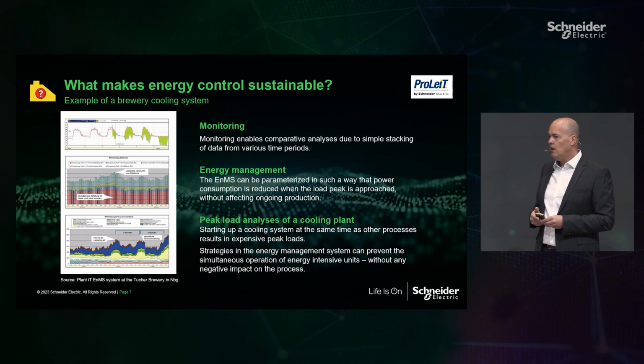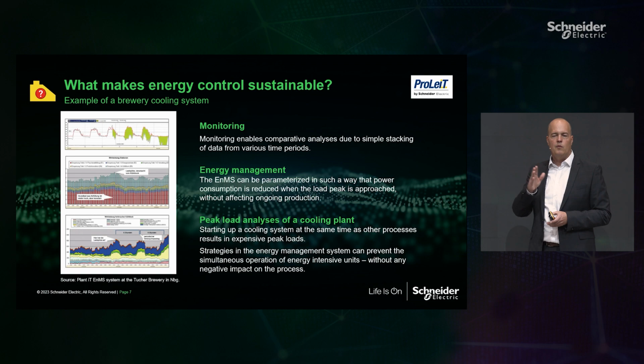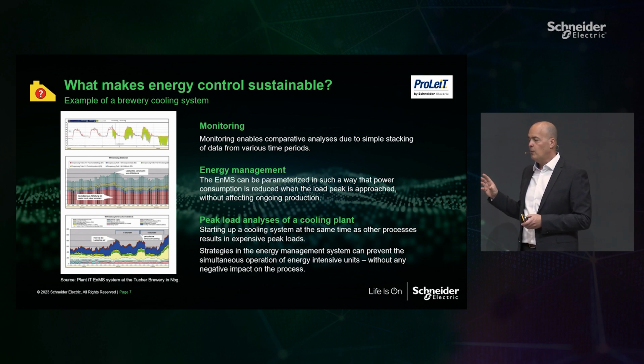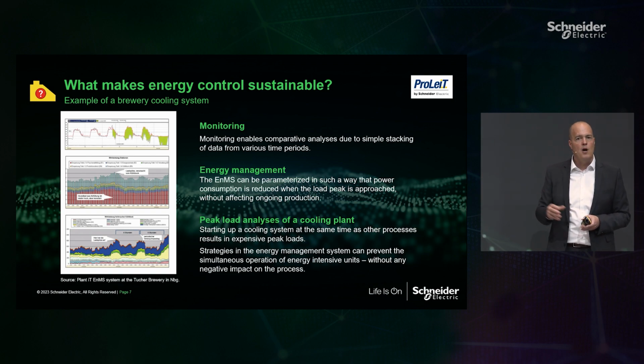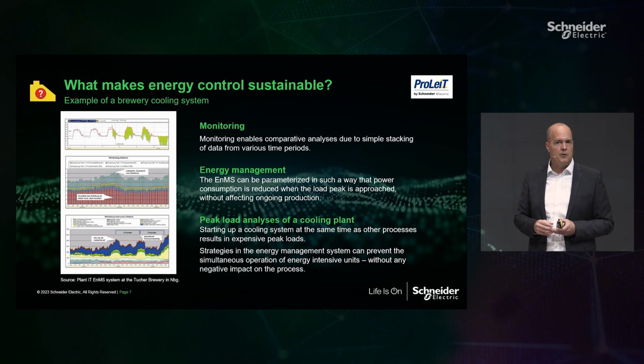Especially these peak load analyzers and the forecast we are doing help the end customer. So here in that kind of situation, we're doing a precast. We look at the future to say, okay, what could be the energy consumption in the future? And therefore you have the possibility, as I mentioned before, for the cooling tanks, and in these breweries they have numerous of them, you can shut down one of these step by step. Of course, you can parameterize it, so just stop the cooling for 30 minutes, for example, and then go to the next tank, and the next tank.